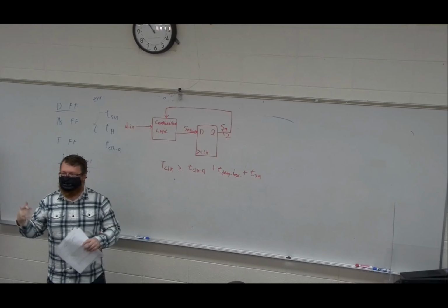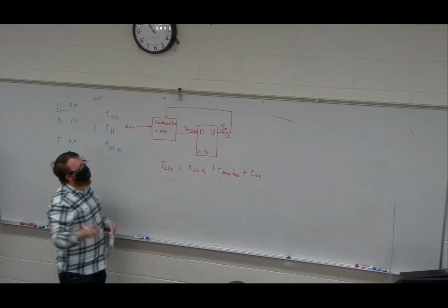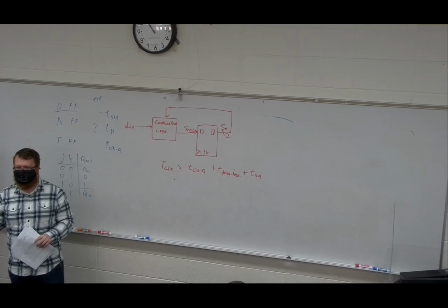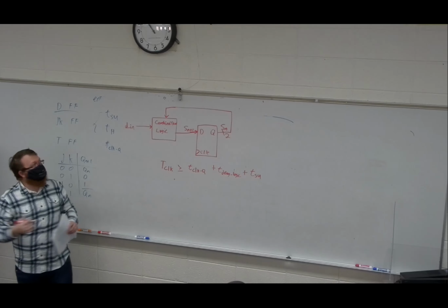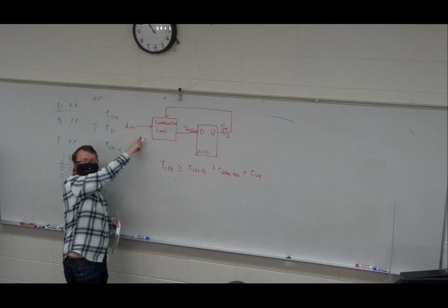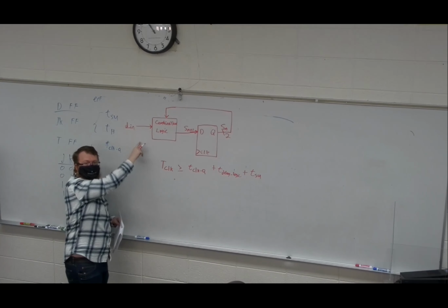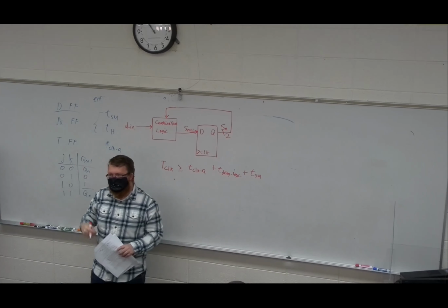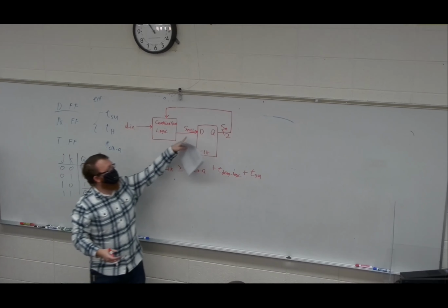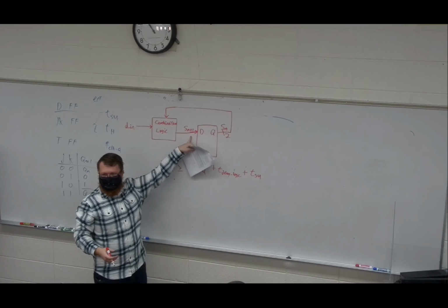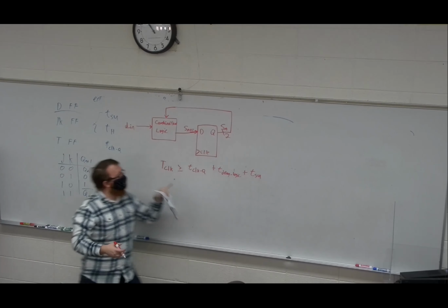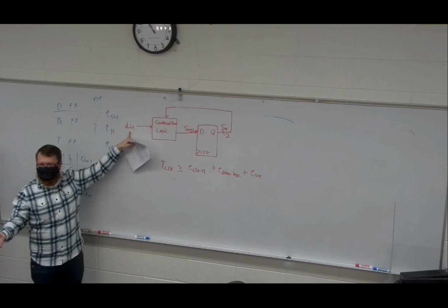Under what conditions if we're red? So the question that this combinational logic is asking, much like your key example that we did before, is: if we are currently red and we have some sort of input, what do we do? Well, if data in is nothing, we stay in red, next state stays red, we update to red and we sit there. What data in might trigger us to go out of red?